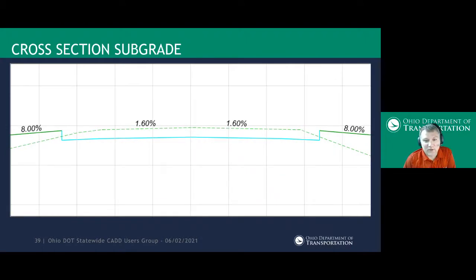So, and then this is what your final cross-section sheet would look like. And you know, one question that's probably going to come up is, how can we remove the slope labels of the pavement? And Eric did a really nice demo actually in the March user group meeting of how to modify the annotation groups so you can customize that for your project or for what you want to see. So I think this should help a lot of folks who really have kind of wanted this, who have asked for this kind of workflow, and you can pretty simply go in and add those into your templates.